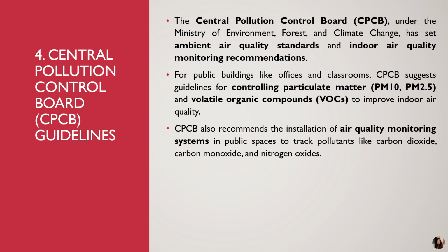Followed by that, we have the Central Pollution Control Board, that is the CPCB guidelines. Under the Ministry of Environment, Forest and Climate Change, it has set ambient air quality standards and indoor air quality monitoring recommendations. All public buildings like offices and classrooms are advised to at least control particulate matter, that is PM10 and PM2.5, and VOCs to improve indoor air quality. CPCB also recommends installation of air quality monitoring systems in public spaces to track pollutants such as carbon dioxide, carbon monoxide and nitrous oxide.